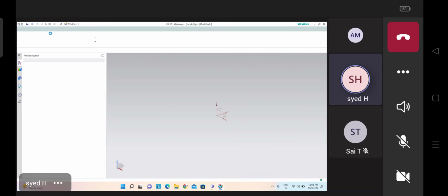Click on, okay, see here you can find the assemblies option also. It's not there. Sorry guys, actually I'm thinking about Team Center software. If it is connected to Team Center, you can find only one model option, and there you can find everything like assembly, drafting, everything here only. I forgot that it's a local license. Here you cannot find it, you have to go for assemblies.